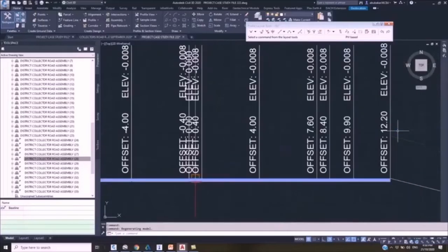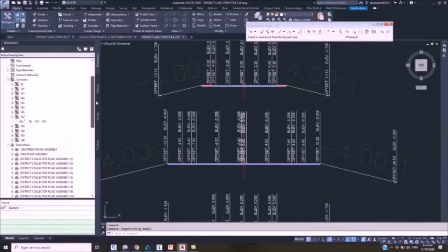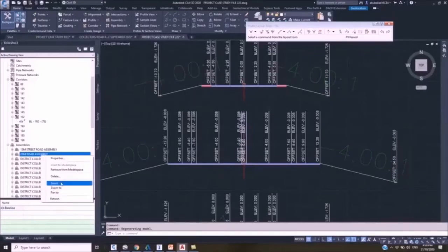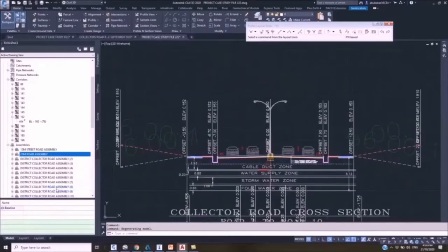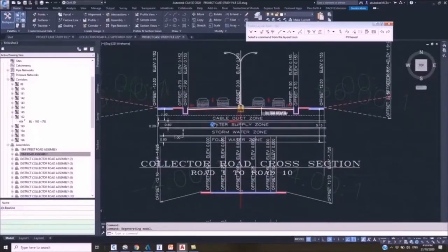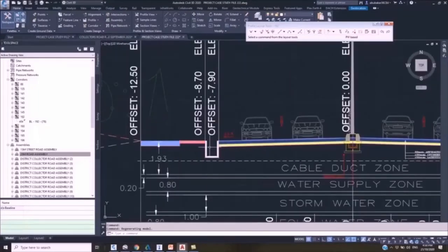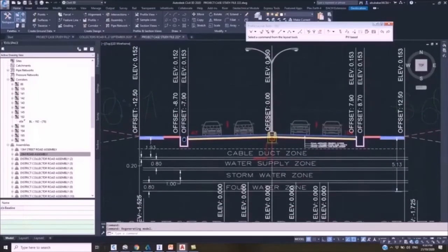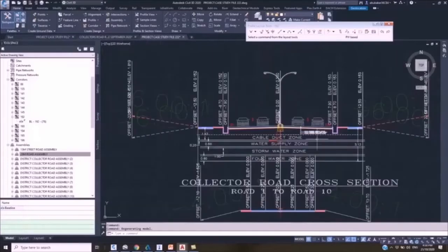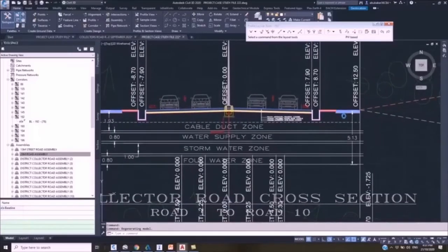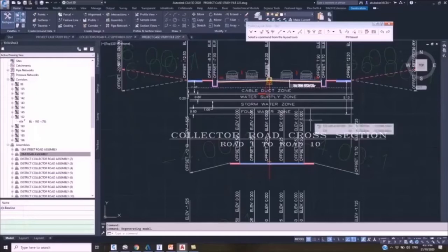The reference is showing 12.5. It has to be 12.5. So what I will do now, under the references, is check the 25-meter road parameter descriptions, select for the review, and zoom to that side. Now, this was our expectation from the coordinations, how it will look. It now tells me that because of the requirements of that extra location, they want an open channel with these conditions as defined for what their section will look like. So I have to change this parameter to reflect these conditions.